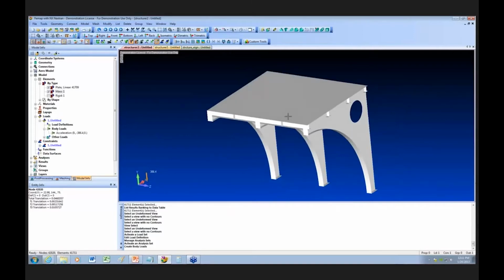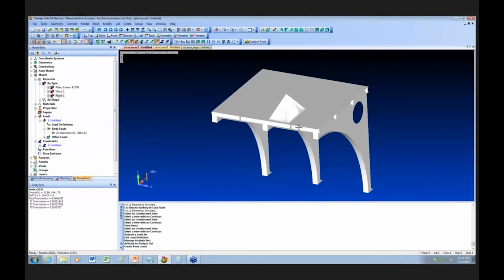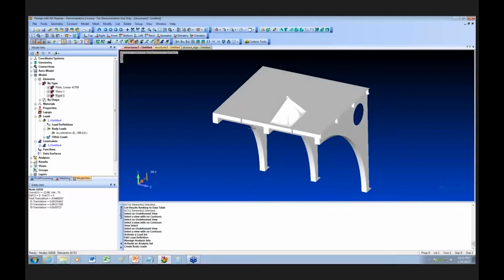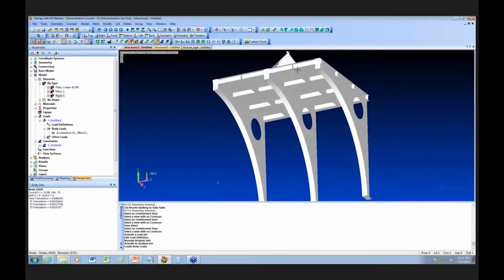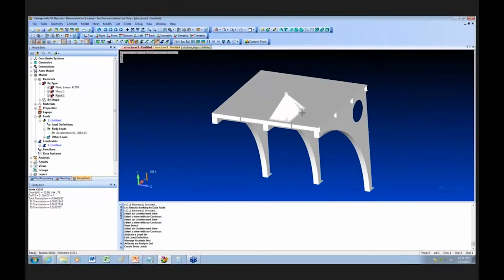And I need to connect it to the surface. And this is made of surfaces and meshed. I meshed the surfaces. So what I'm going to do is connect the rigid element to the surface here. Okay, and this is an RBE2. And what an RBE2 does is it will take all these degrees of freedom, and all these degrees of freedom, and it will couple it to this point right here, thus making this area a very stiff area. And if you drop a very stiff box, that might be exactly the proper modeling.